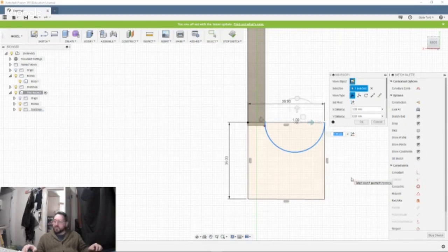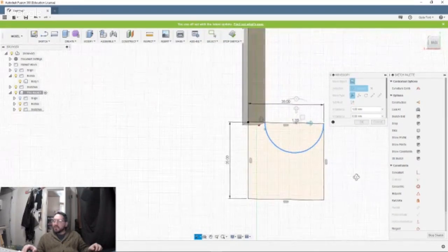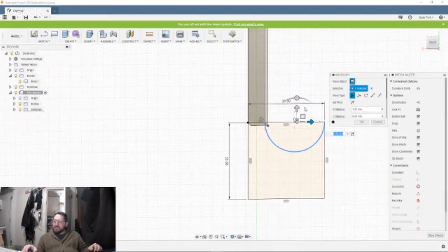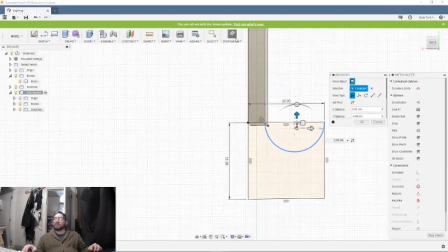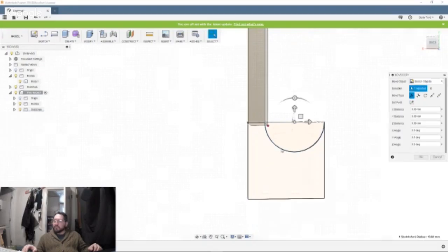Oh, it's not gonna let me move that. It's not gonna let me move it. Nope, not when you're in a sketch. You can't move stuff in a sketch. Oh, I did not know that. You can move the whole sketch, but you really don't want to. The move tool is more for placing solid objects. You really shouldn't move your modeling equipment. If you need to move it, you need to redraw it in the correct spot.